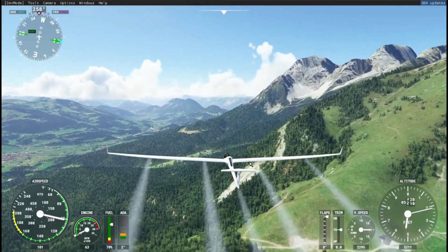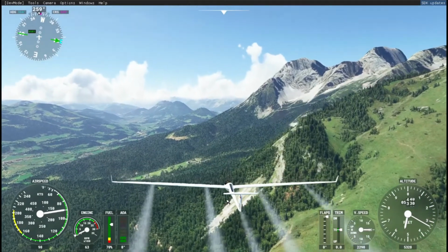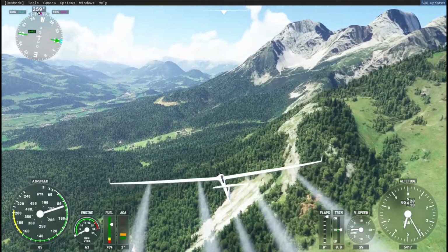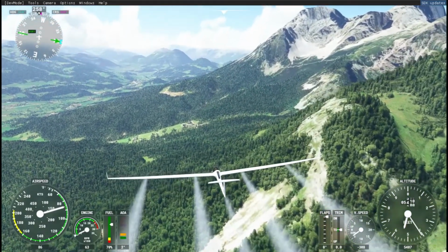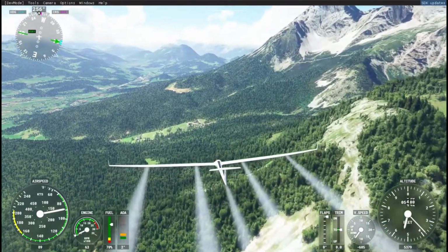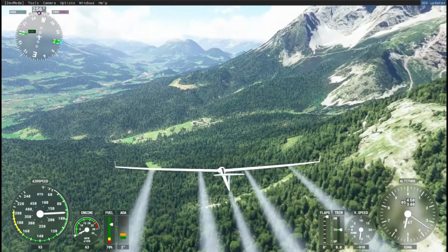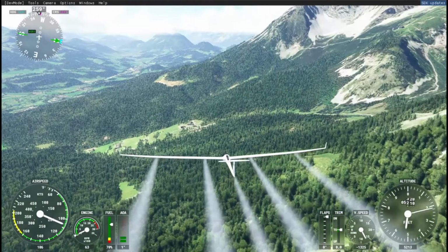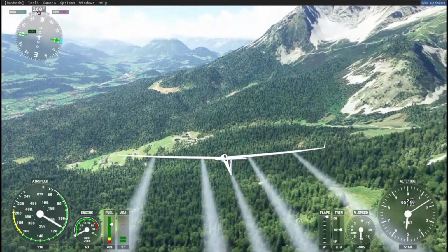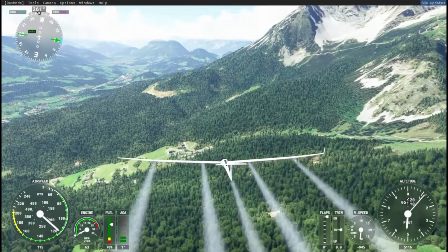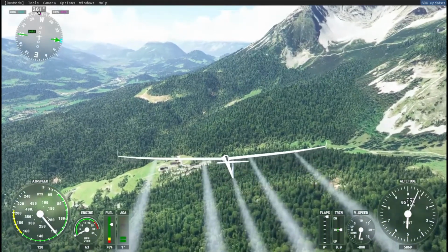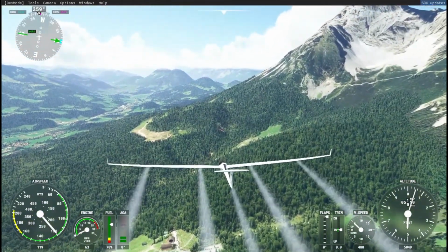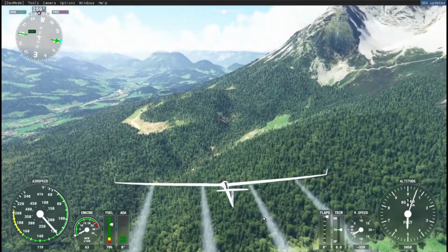You see, there are the outer tanks, the tail tank, and then the 2 inner tanks. The largest tanks are the 2 inner tanks for good reason, and the tail tank always empties first because you avoid ending up in a tail heavy situation, which would be a nightmare. So you'll see the tail tank stop dumping shortly, I think. There you go, the tail tank has stopped dumping.